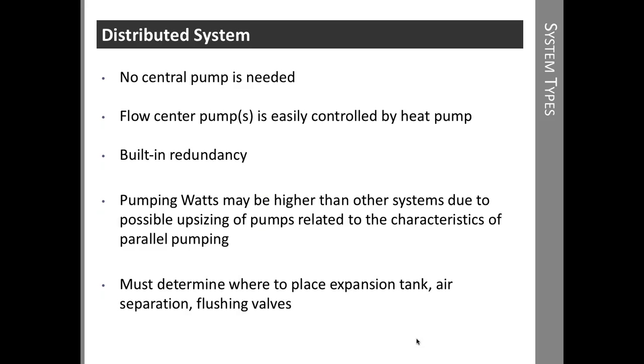The disadvantage is, in almost every case, the pumping watts are substantially higher when you have all these pumps in parallel. There are two reasons. Number one is you just have a lot of pumps, but secondly, parallel pumping allows you to have higher flow rates, but the same head of one flow center or one pump, depending upon how many pumps are on each flow center. And it's sometimes difficult to figure out loop pressurization.